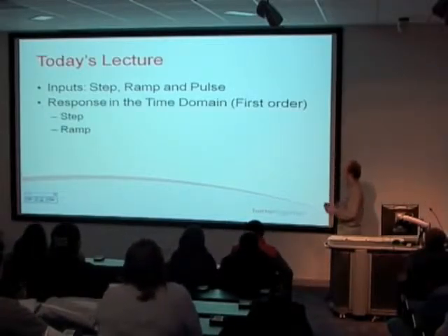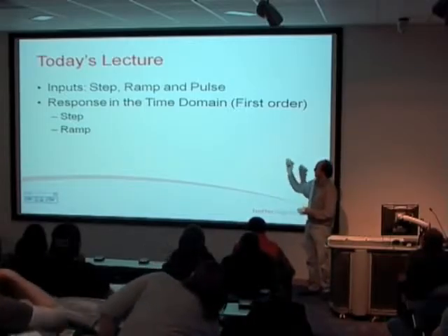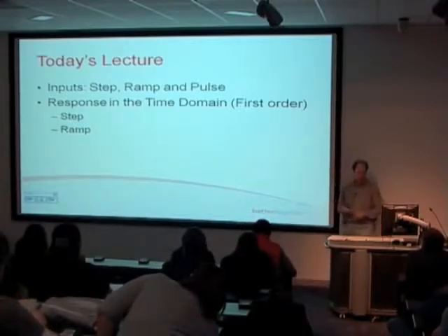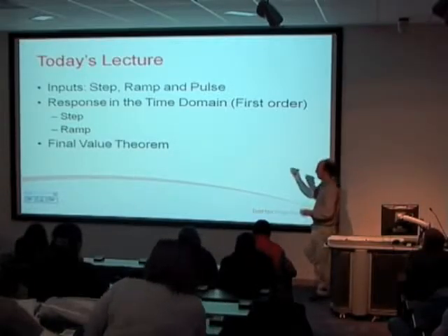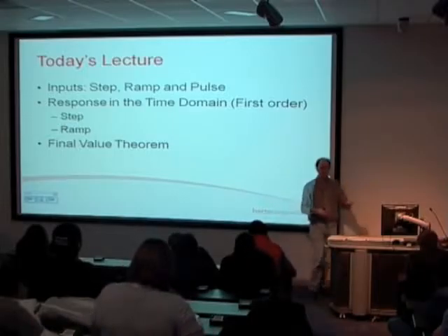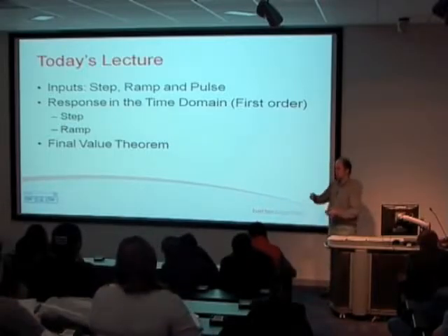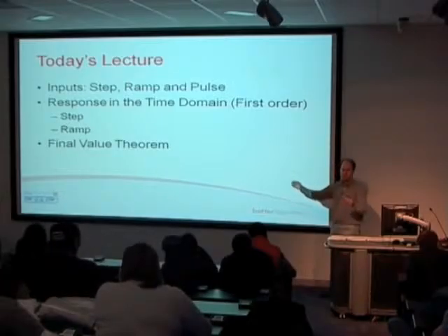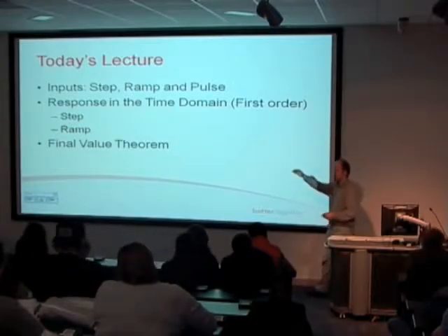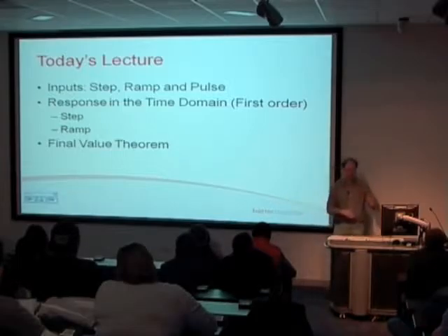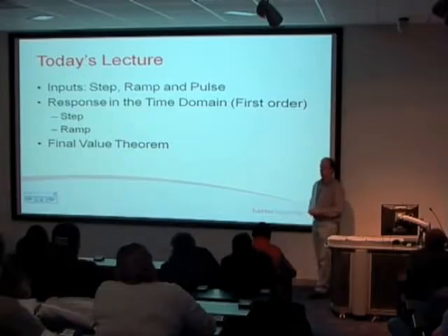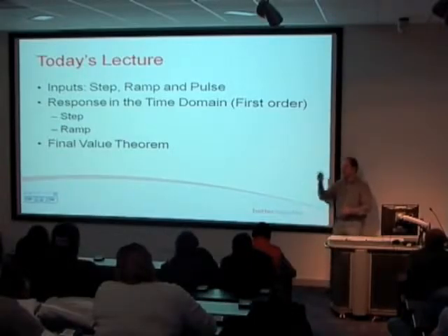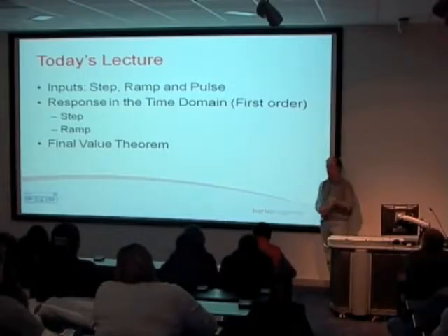Like I said, this week we're just looking at first order systems, and we look at the response in the time domain of a step and a ramp. And then there's the final value theorem, which we'll run through, that allows you to find, after time has gone on for a little while, the final value of your system. Say that there's a slight error in your system, you can look at the final value. It's looking at, as time tends towards infinity, you'll get a steady state, and this will give you the value of your steady state.